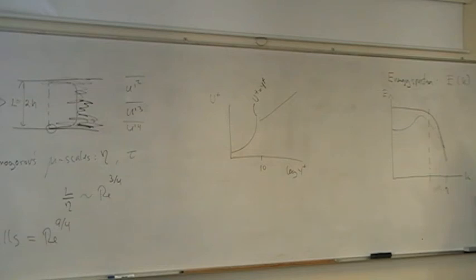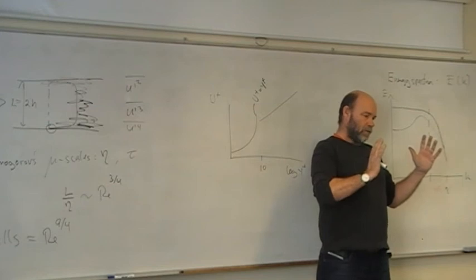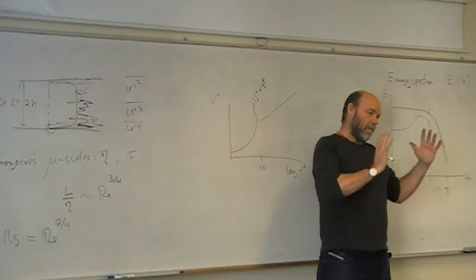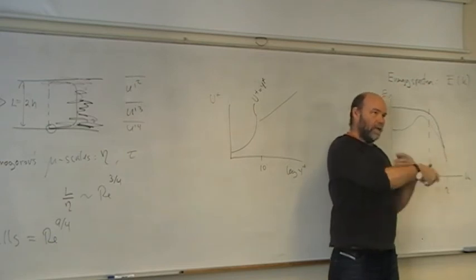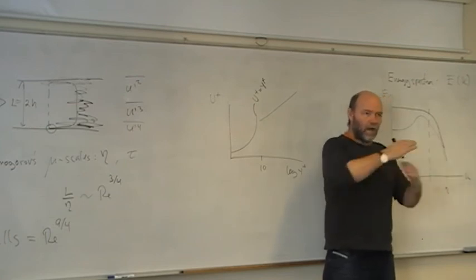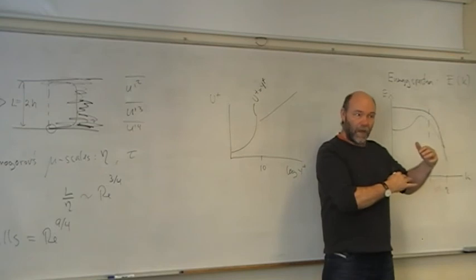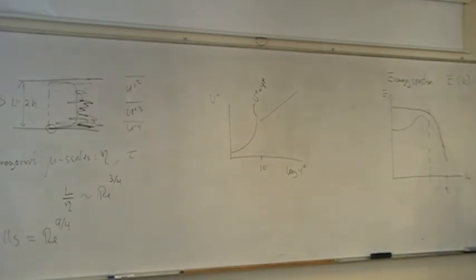Will you have a tendency to get too large velocities since you don't dissipate? No, because remember, you have one constant driving force in the problem, and then what's going to happen with this force? You're going to need some viscous forces to damp out the driving force in the problem, but you don't have velocities enough and viscosity enough to damp it down. So it's going to be very unstable indeed. I don't think you can get any reasonable results whatsoever, even with very, very small delta t. So you will be in trouble.